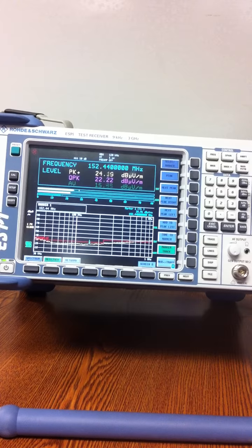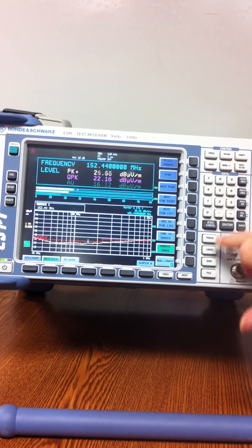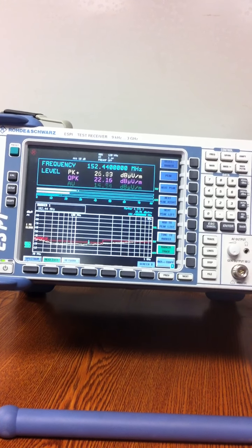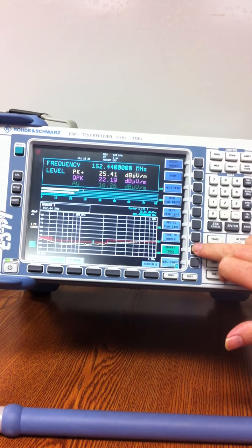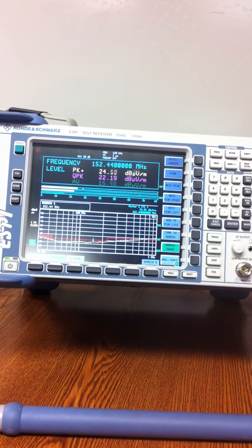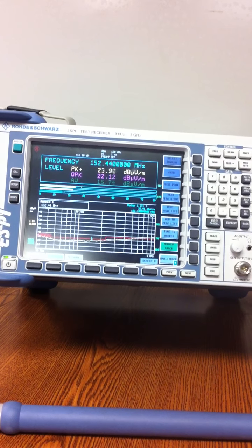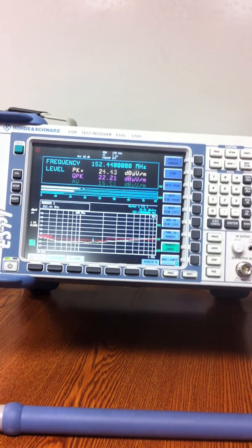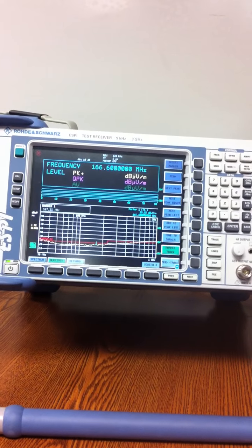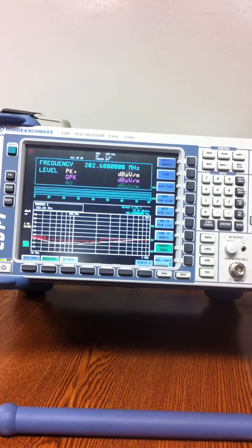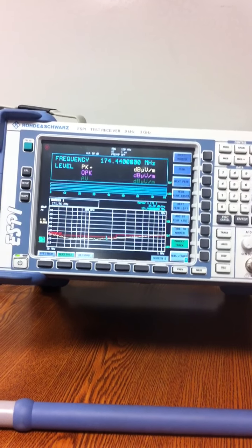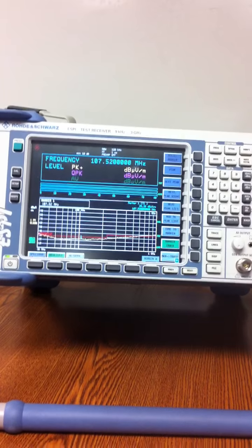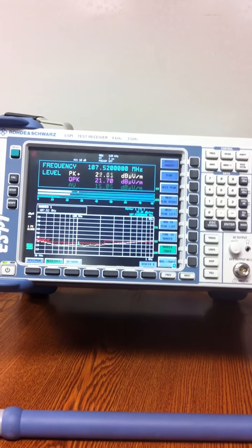Then you can press the marker button, and for some stupid reason, you have to press that button twice. First, second, so it's highlighted again. Once that happens, just look how the frequency moves if the cursor moves. So the cursor and the measuring frequency are actually the same. If you find a hill, just search around and you'll find the actual value that happens at that frequency.